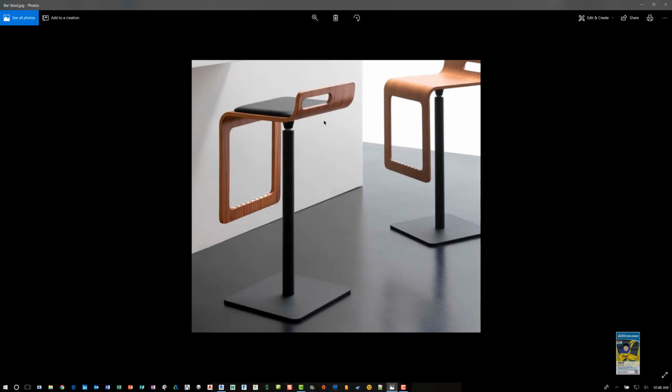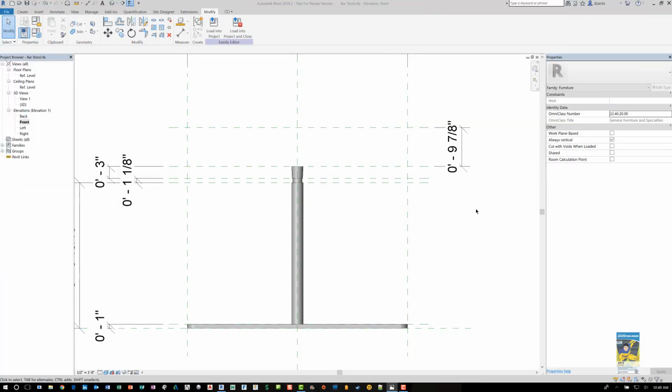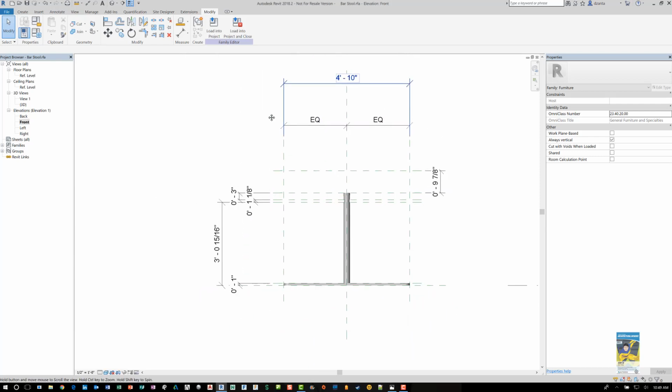So if this is the front and this is the back, we want to head over to the right or the left side to do the profile. This, bend, horizontal, bend, vertical, kind of vertical, looks a little slightly bent, and then let it extrude in that linear direction. Okay? Again, since we've done a little bit of work, we need to save our work.